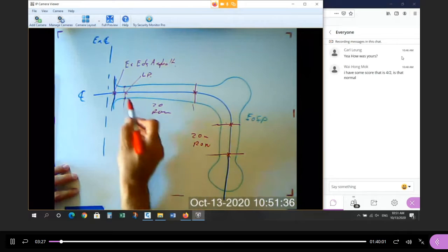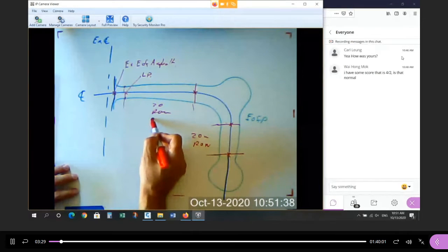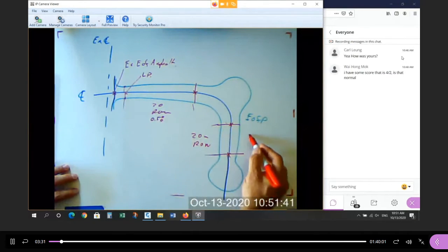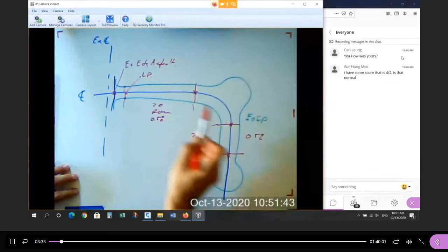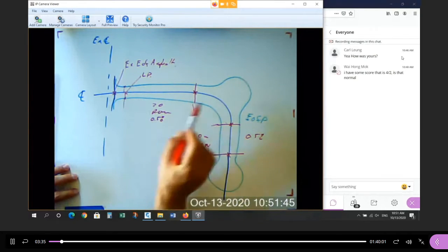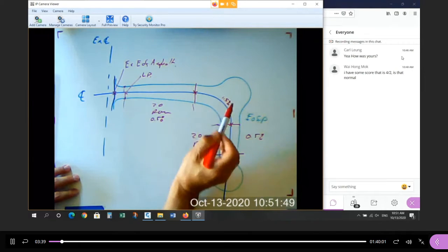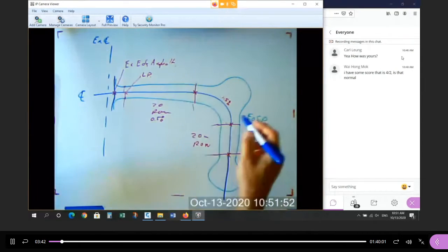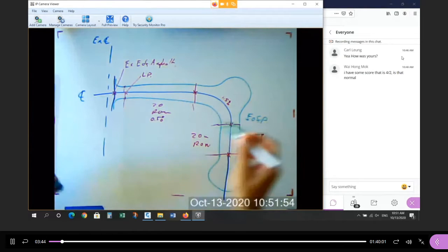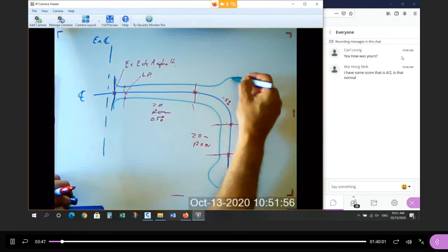And we determined that in the standard 20-meter right-of-way, we want 0.5%, which is the typical minimum. Between here and here, I calculated, you have to check your own, I calculated 1.5%, right? I calculated the length along the gutter. This is the length of the gutter.